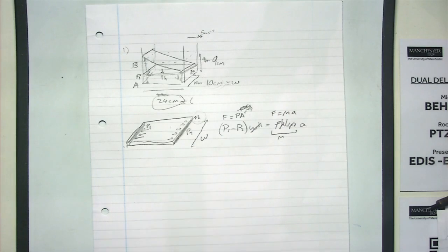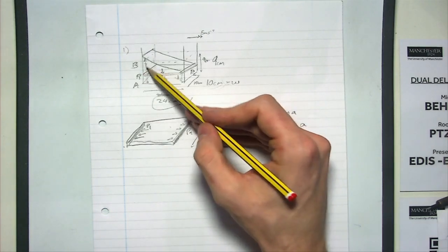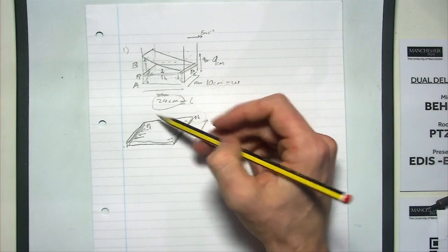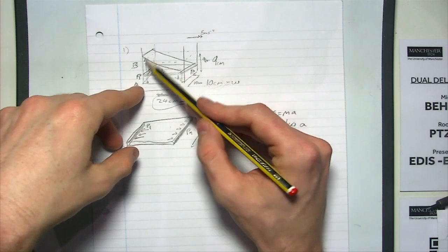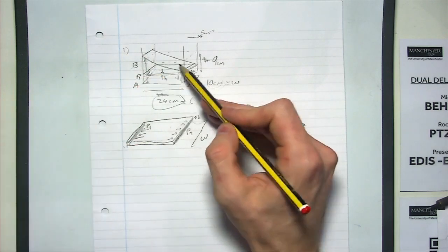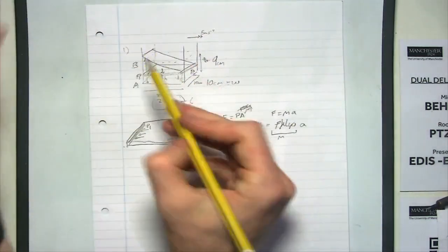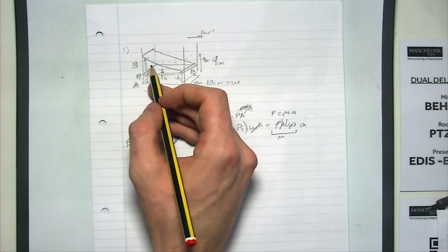So we know that the pressure increase on this side, this P1 pressure, is caused by this depth of the tank, and then there's a little depth here that causes the pressure here. Are we okay with that? I.e., there's a small increase of depth here that contributes to a larger pressure in this region of the tank. Because you've got to remember that the tank's accelerating to the right, so the force of the fluid is pushing this way. So this pressure is to do with the depth here. Are we happy with that? Does that make sense to people?